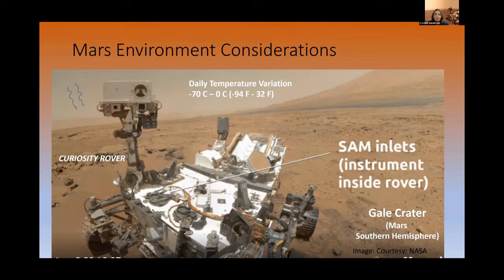The carbon dioxide environment, coupled with the low atmospheric pressure, about 1/100th of Earth's atmospheric pressure, introduces challenges for the high voltage electronics. So special potting has to be used in the HV connectors to prevent electrical arcing. Particle radiation from solar wind and cosmic rays can be detrimental to electronics, 13 times that of Earth, which is why these missions fly radiation-hardened electronics. This makes the electronics much less susceptible to damage or malfunction caused by the radiation.